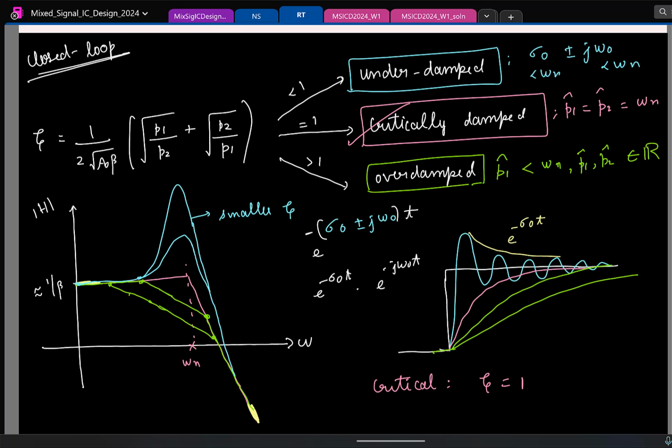So now again, remember we all started with seeing what will happen if I have an amplifier and the amplifier has 2 poles, and I am taking the 2-pole amplifier, putting a negative feedback, and I see I can have all these 3 combinations. Now my goal is to make sure that when I put it in negative feedback, I end up with a critical damping case. So we'll have to see how we can design the amplifier's parameters to meet this. Okay, that should be our goal.